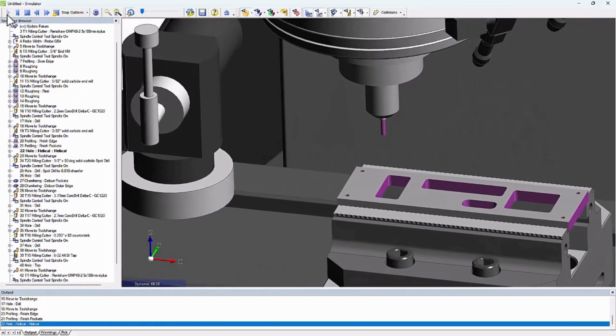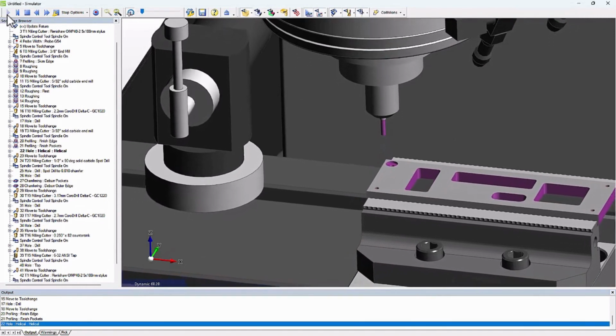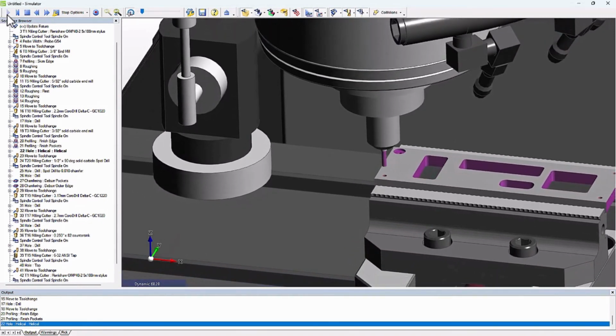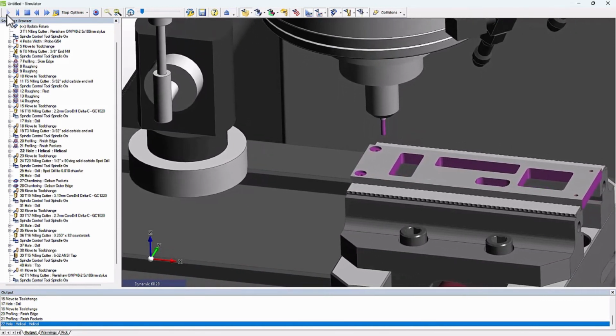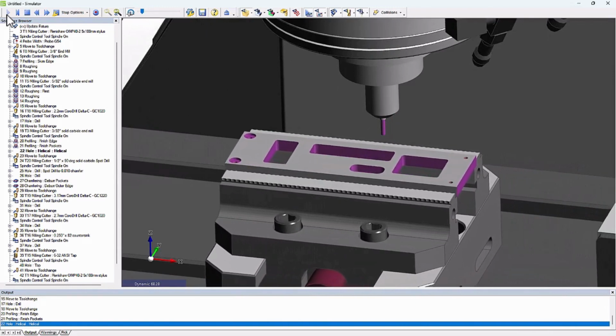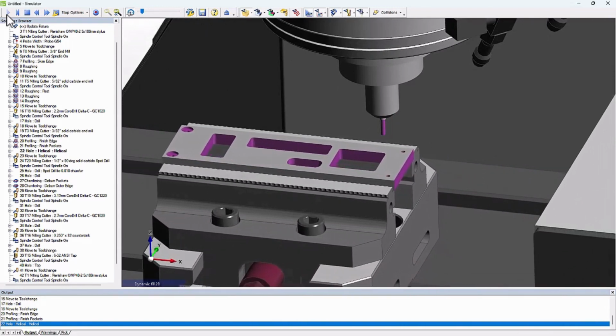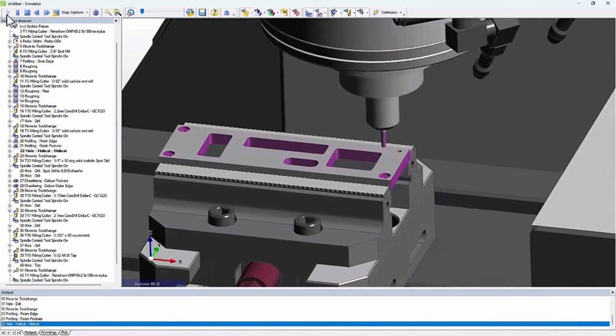As we move into finished machining, the finished machining is done flawlessly, including things like the helical motion. We are confident that cutter compensation will output at the required time, turn off at the required time, and we'll be able to run our CNC machine with ability to run either under centerline or geometry compensation, whichever our company prefers to use.